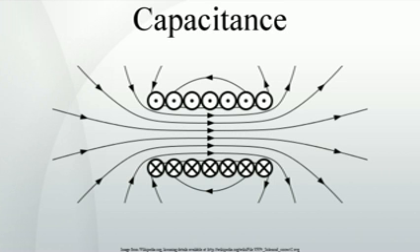A Fourier transform in time then results in an expression where the susceptibility is now a complex function, with an imaginary part related to absorption of energy from the field by the medium. This gives the complex permittivity. The capacitance, being proportional to the dielectric constant, also exhibits this frequency behavior.